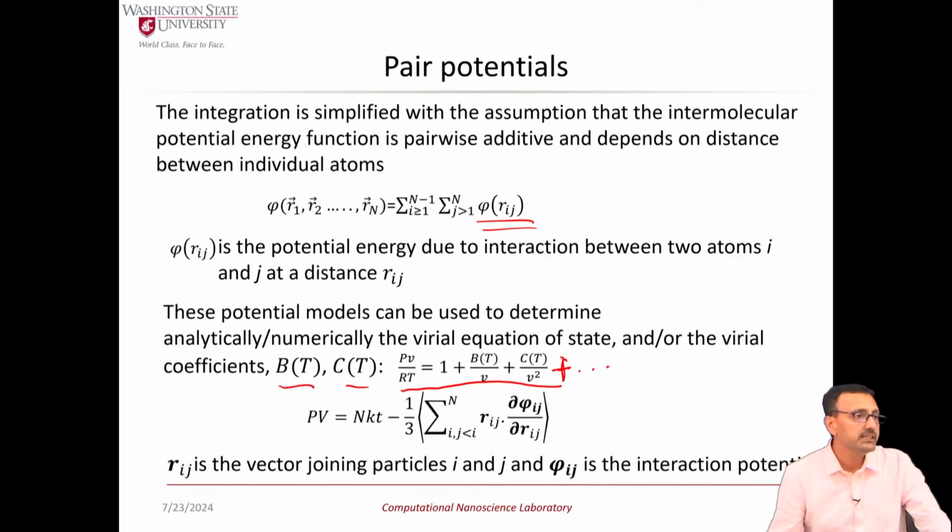If you are interested in the mechanical properties of a crystalline system, on the other hand, what you can compute from the virial is the atomistic level stresses, or the stress tensor actually, for each atom in that crystalline or amorphous system.